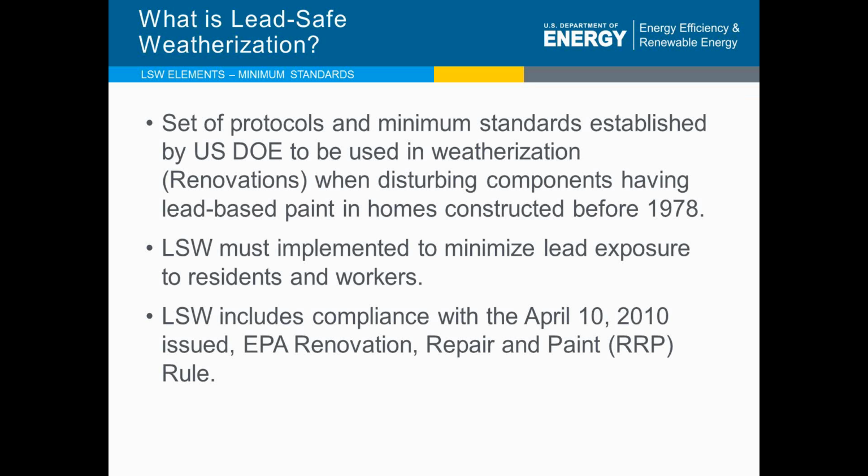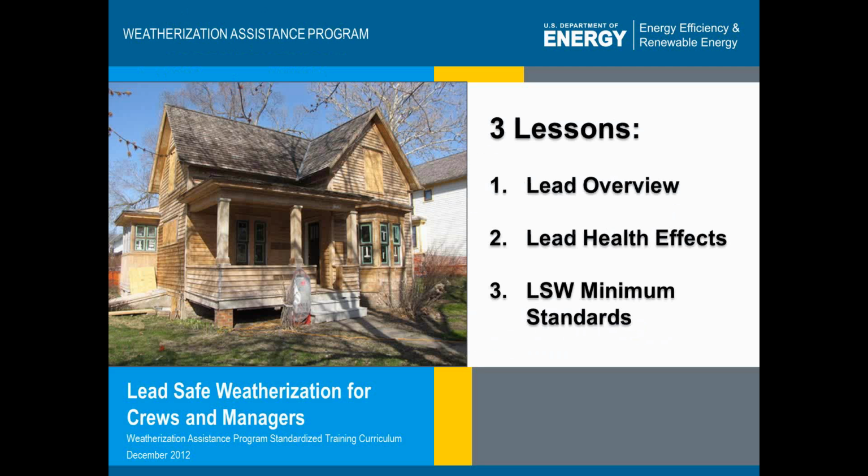And if we are disturbing leaded surfaces of the components, not the entire house, just the components that we're working on, we have to use lead-safe weatherization techniques. And again, as of April 10th, 2010, this does dovetail with RRP, or the EPA renovation, repair, and paint rule.